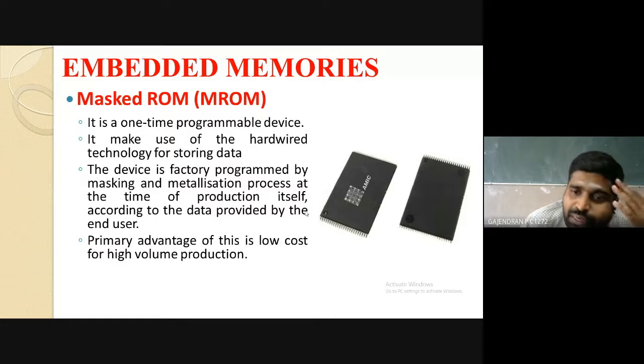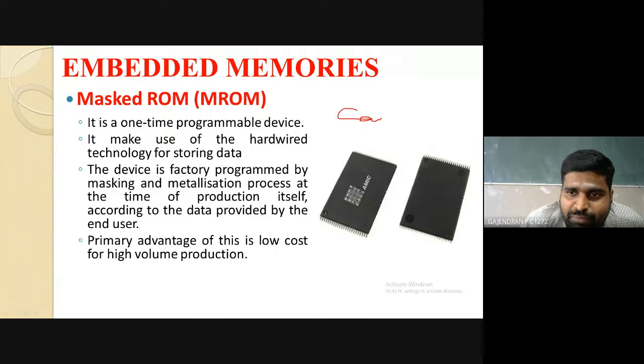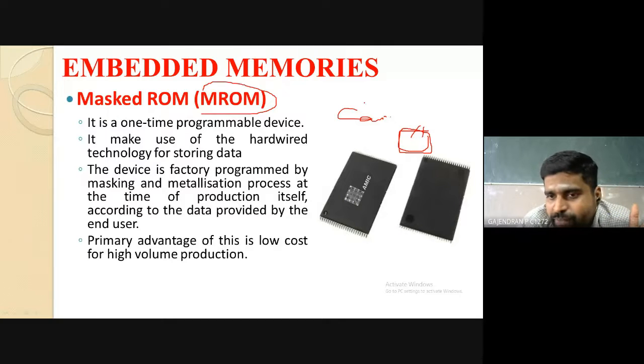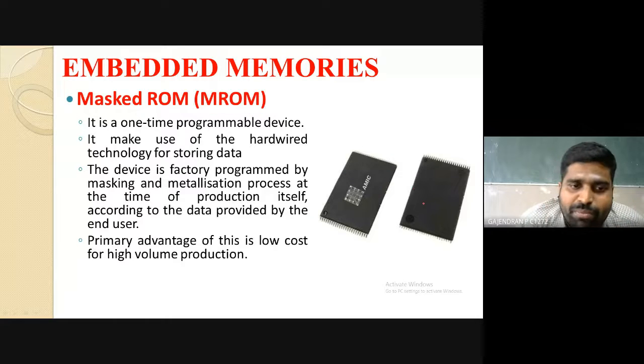For example, we buy a calculator, a Casio 9MS. There a set of code stays exactly as it is. We are not going to update the calculator code, so I can simply use the mask ROM itself. Okay, that is the idea behind mask ROM: huge volume production, low cost. It is programmed in the factory during fabrication, and you can't erase it.